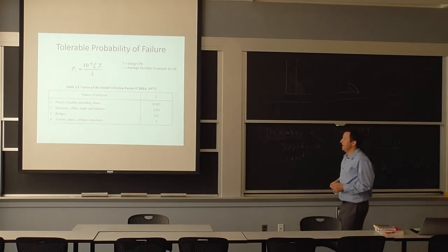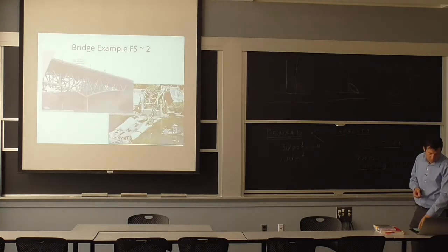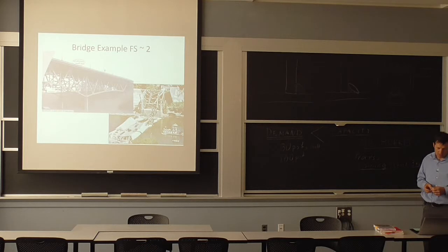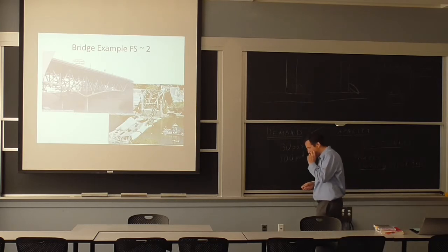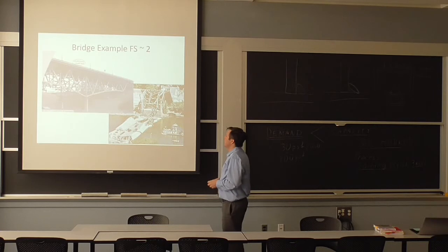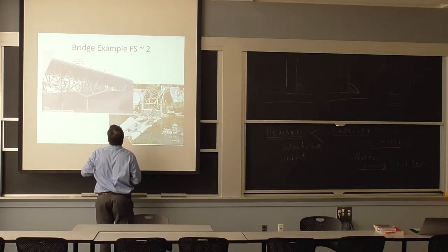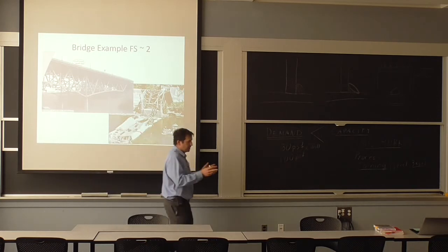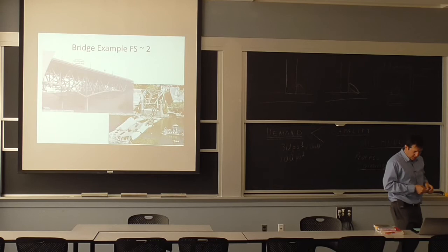So it's really part of the overarching concept, and I've mentioned bridges because that's something that I did work on, the bridge collapse in Minneapolis that was built in the 1960s. So no problem with the processing of the steel itself, but they did have rolling contact supports to allow for the expansion and the contraction of the bridge, and these were really rusty.